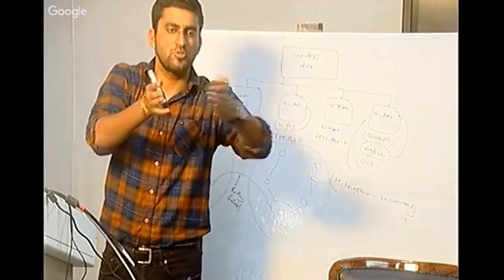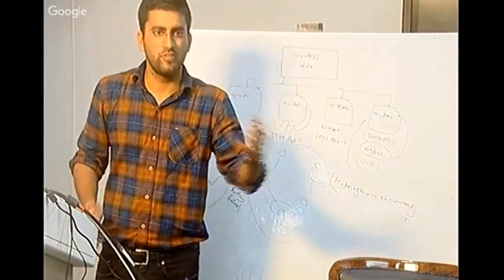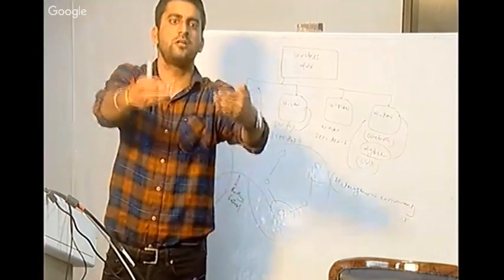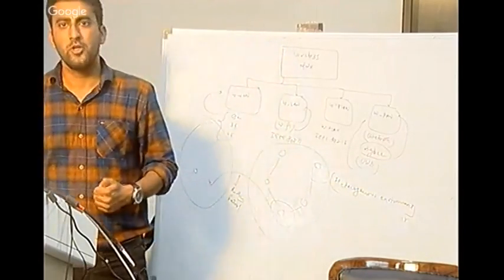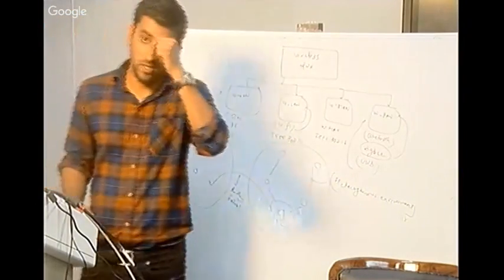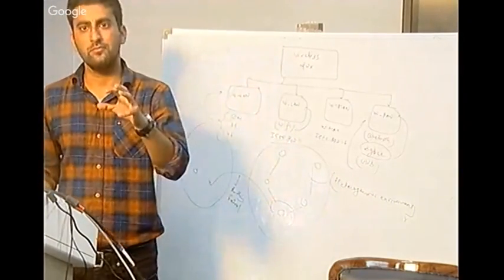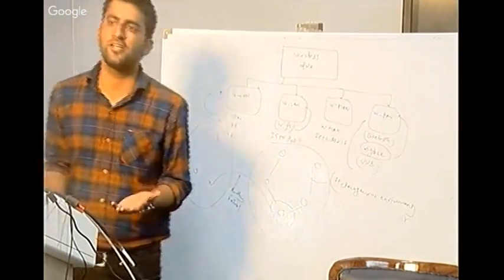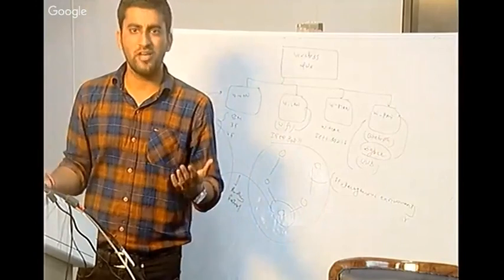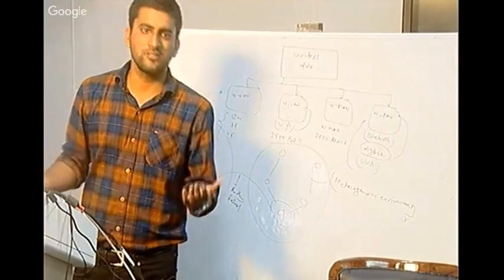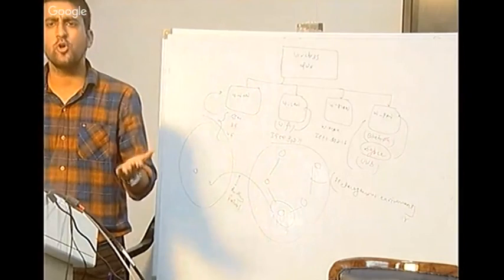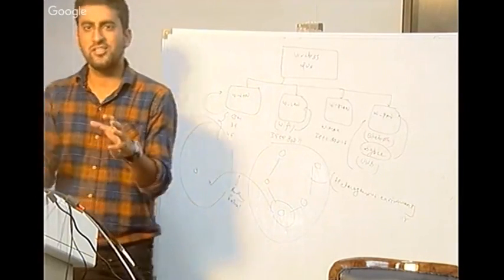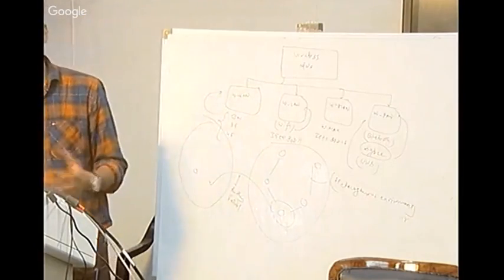That means the transmission is taking place between those nodes which have high energy, and the rest of the nodes in the cluster are just transmitting their data to the node which has high energy. That's why power is a very important thing in a wireless sensor network, because everything is dependent on it. Once the node power dies, the entire sensor network is going to die. One could think of just going and changing the battery, but it's not possible, because there are some locations where you cannot just reach and change the battery.